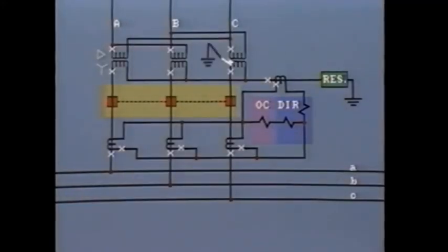Now, for an internal fault, current will flow into the transformer from the feeders through the fault and circulate up the neutral. The circulation of CT secondary current is such that the directional unit picks up. Also, the two currents add in the operating coil and so trip the relay. Even if there were no backfeed into the fault from the feeder, there would still be sufficient flow of current through the relay in the right direction to cause operation.